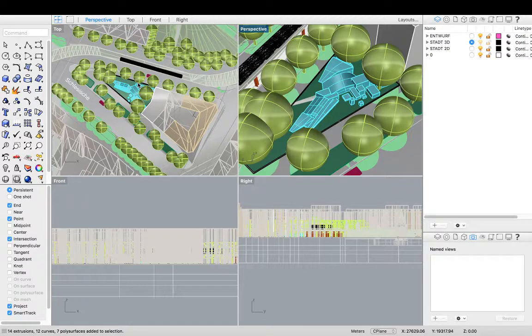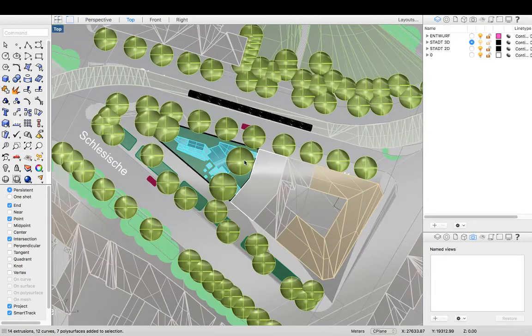So the first thing we're going to do is take a plan line drawing using the Make 2D command. And we're going to use the Make 2D command for all processes of converting 3D data into a DWG line drawing. So the first thing we need to do for our plan drawing is to select our viewport.